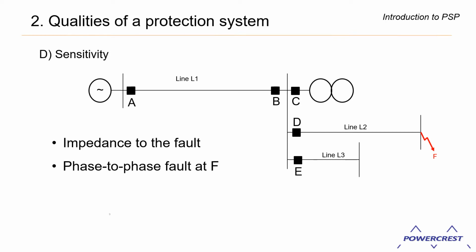That's if we don't have any rotating plant in the immediate vicinity. Rotating plant being motors or generators. So as a rule of thumb, we always have the phase-to-phase fault being around 86% of the three-phase fault at a given location in the power system.